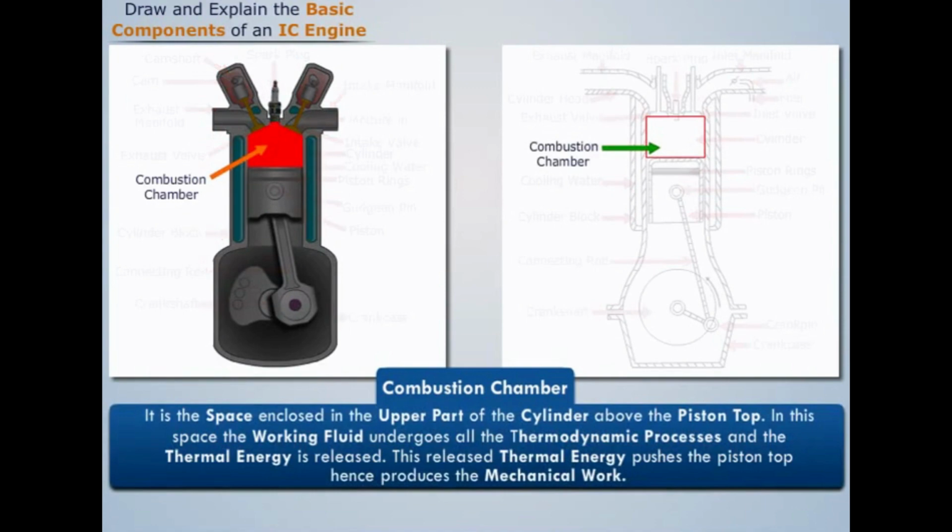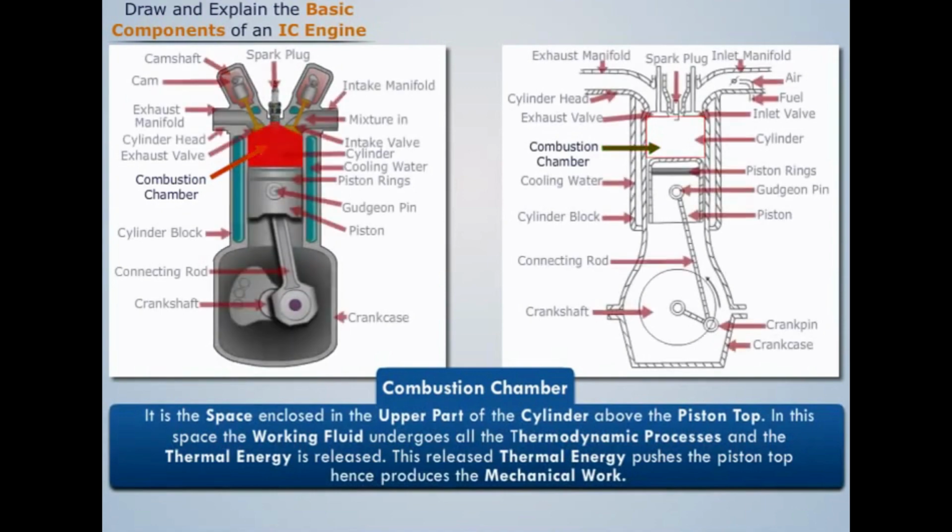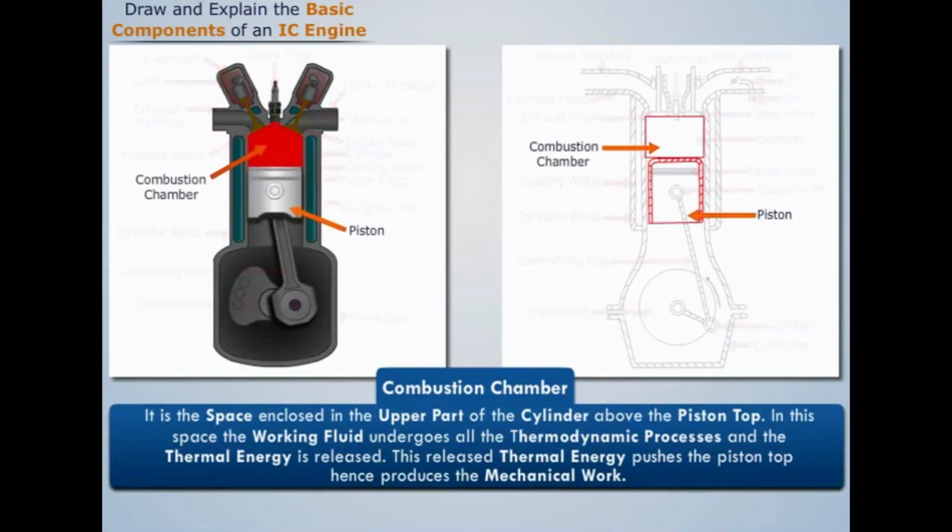Combustion chamber is the space enclosed in the upper part of the cylinder above the piston. In this space, the working fluid undergoes all the thermodynamic processes and the thermal energy is released. This released thermal energy pushes the piston and hence produces the mechanical work.